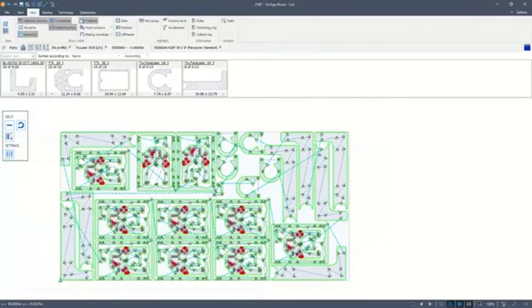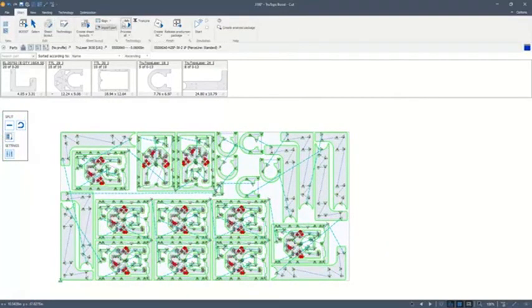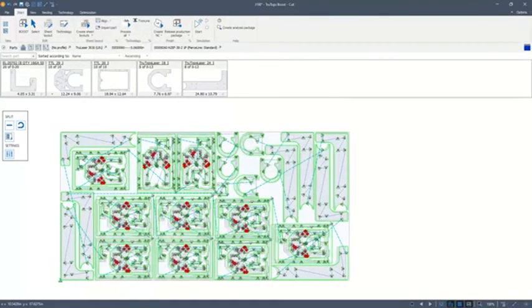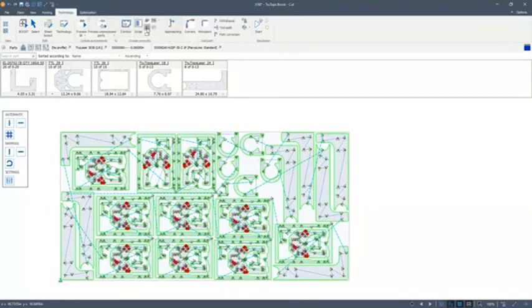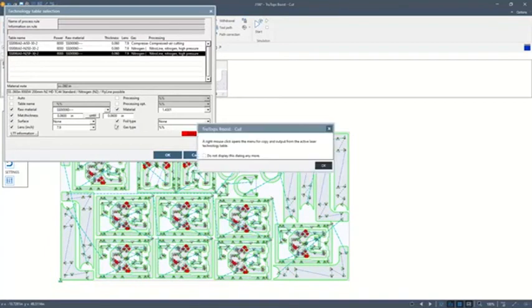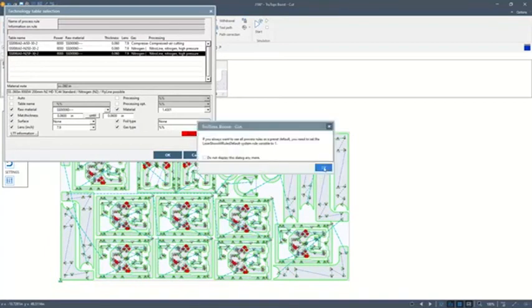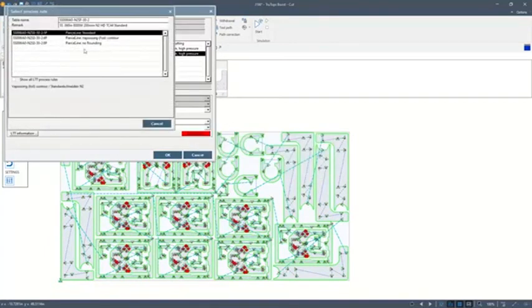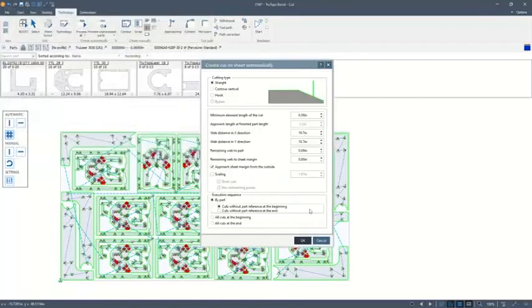Okay, now that I've made some processing changes, let's spread the parts out more evenly, do some distribution. Okay, and one last thing, rather than have a large skeleton to deal with, whoever's responsible for the part separation side of this after the sheet is cut, go ahead and make their life a little bit easier and safer by throwing in some grid cuts.